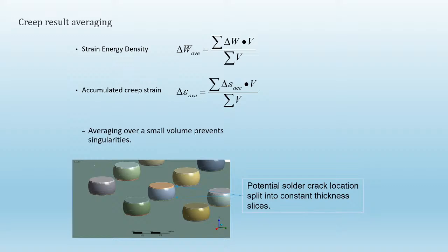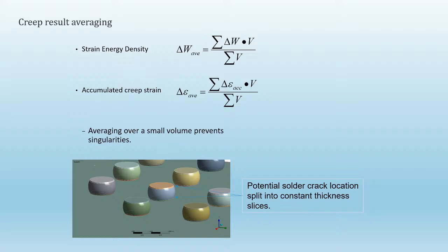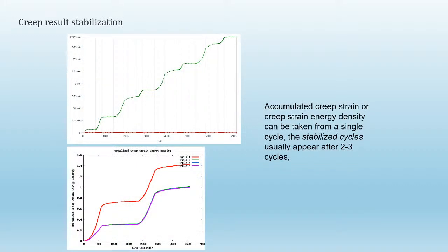Do we simulate all the cycles or just a few cycles to extrapolate? You would only need to simulate a few cycles to extrapolate. And that's actually great timing, because that's what it says here. There's an idea of creep stabilization. If I want to do actual thermal testing, I would have to do thousands of cycles, maybe sometimes tens of thousands of cycles, to make sure I have the durability I need. We can't really do that efficiently in computation.